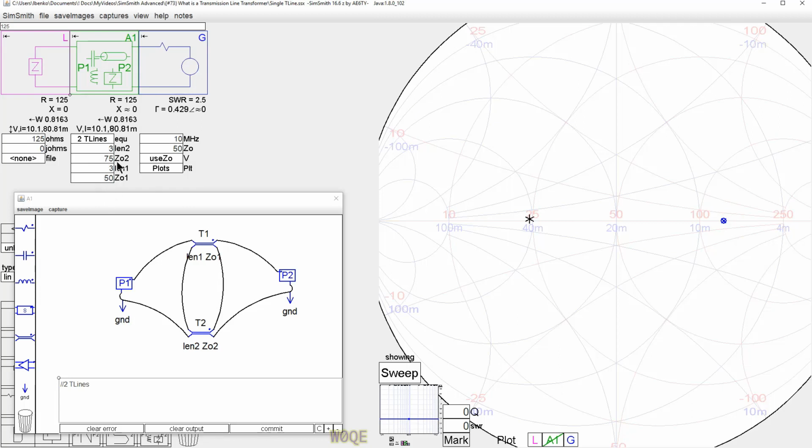And we could have done the same thing with them in parallel. You can have a 50 ohm and a 75 ohm transmission line in parallel. They look like, I'm going to use the same formula as you use for resistors. So it's 1 over 50 plus 1 over 75 equals 1 over, a 30 ohm transmission line. So you can get different impedance transmission lines than you think you could by having transmission lines in parallel. Again, if the length of this one changes by a foot, we don't see a lot of action. This is just another interesting thing to keep in mind.